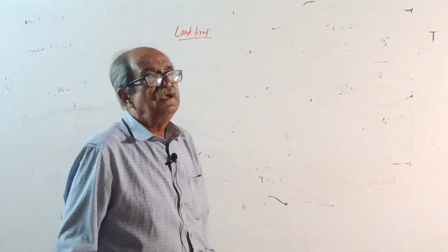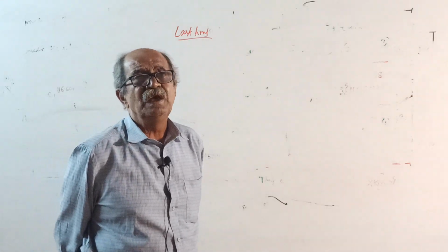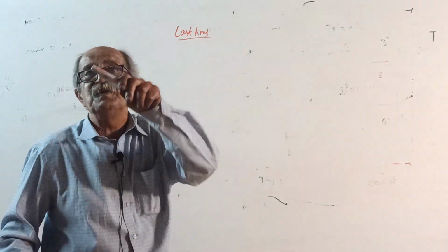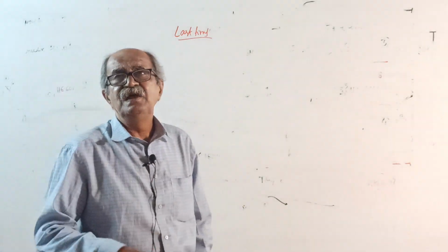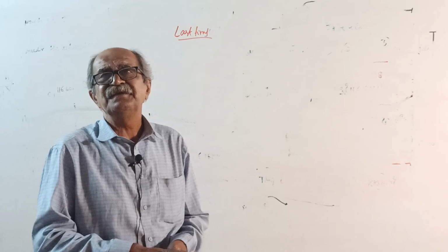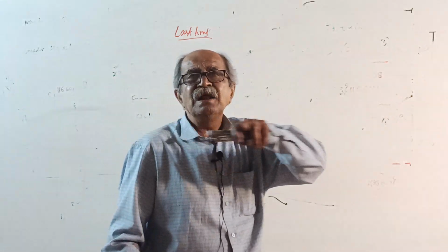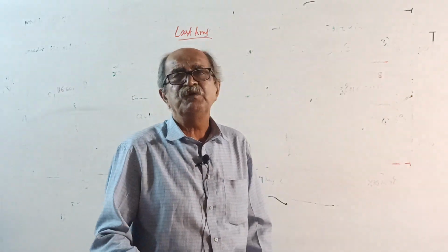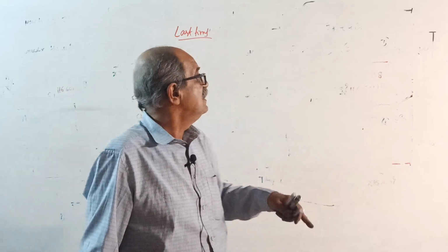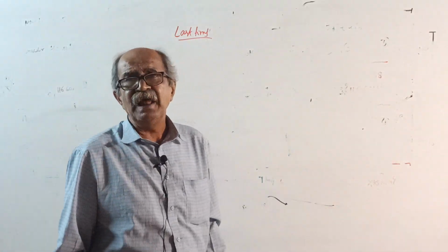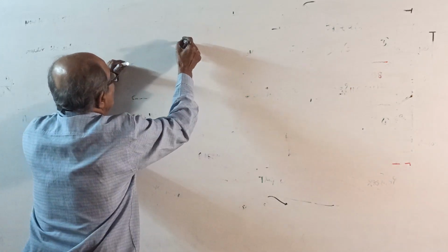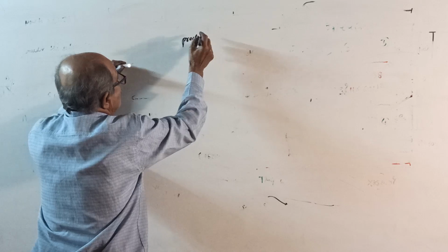But in a question, suppose they want moment of inertia about any random axis like today's class question 138, then don't waste time locating the centroid and don't mark xx, yy. Directly mark those given axes and find moment of inertia by dividing into parts only. Once again, divide into parts, apply parallel axis theorem and get the answer. I'll give a practical example for this one.